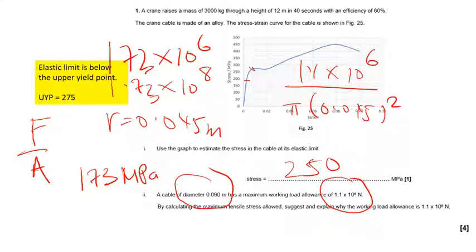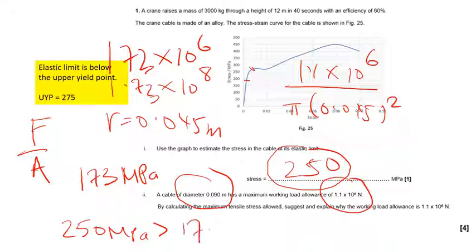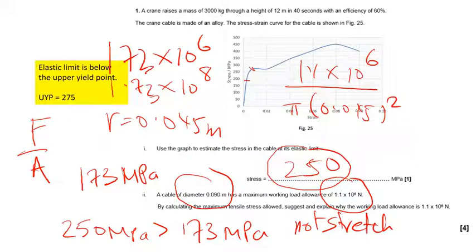So that would be 1 mark, and because the maximum, what is the maximum? Well, we said it was 250, isn't it? So 250 megapascals is bigger than 173 megapascals, and it will not stretch too much. So there's less chance of permanent deformation.